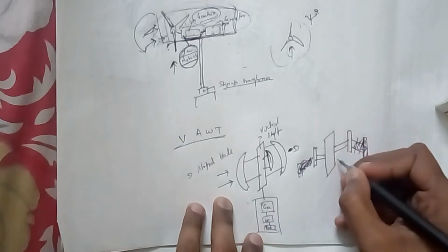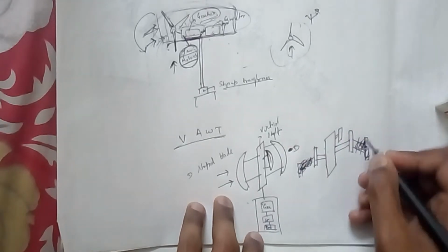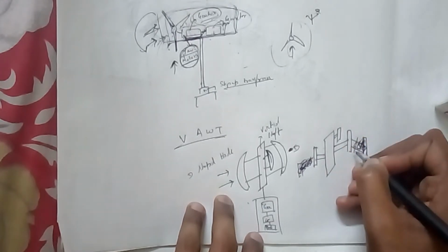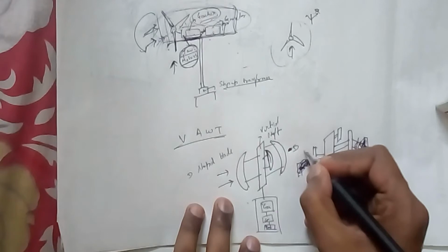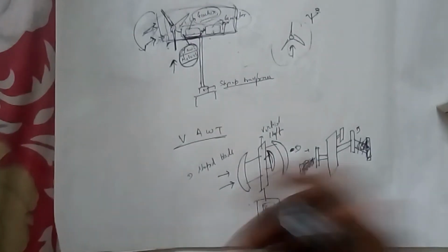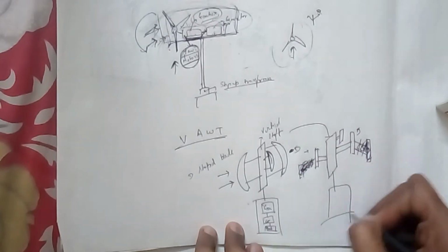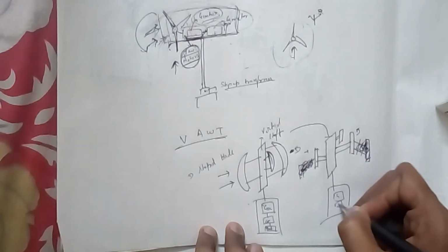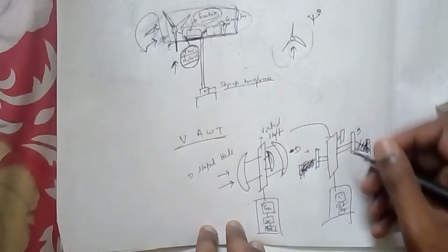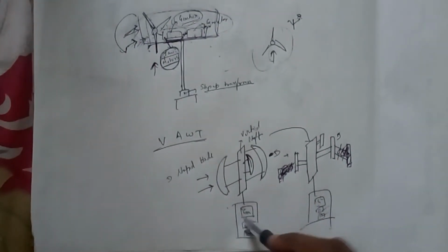This one, and there is one at the end corner, this one. So they rotate because it's H type. You're getting it, right, H. Same thing, wind comes, they rotate clockwise or anti-clockwise depending on the wind. This is your vertical shaft. The rest are the same: gearbox, generator, battery. Basically the working is the same.